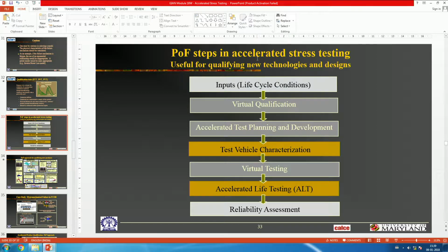This is an example of EV testing that we did many years ago, back when flip chip on board was brand new. This was a company sponsor we were working with who had not fielded that technology yet, but their R&D group wanted to evaluate flip chip directly on board, and what drives it is cost. People went from expensive substrates to just putting the die directly on the circuit card to minimize cost, flip chip joints. So this company wanted to evaluate how robust that technology is going to be.